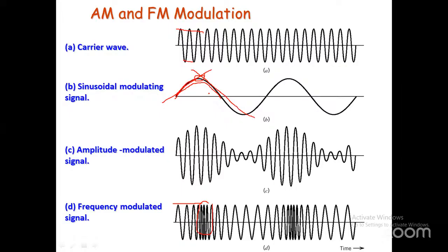As the message is decreasing towards its negative minimum value, it is called negative slope. For negative slope, the frequency gradually decreases. At this negative minimum point, it has minimum frequency. Then again, for positive slope, it gradually increases. At this point, we have maximum frequency.